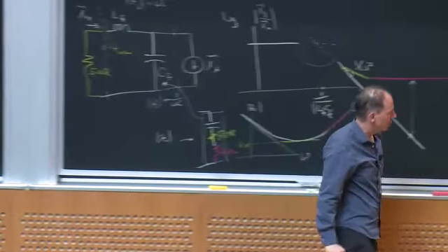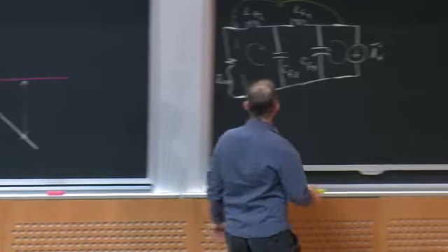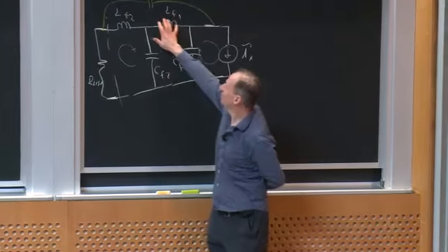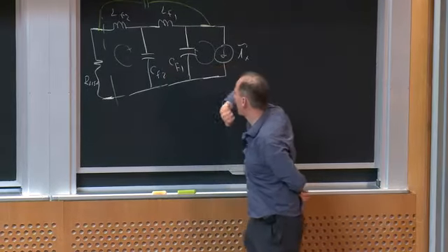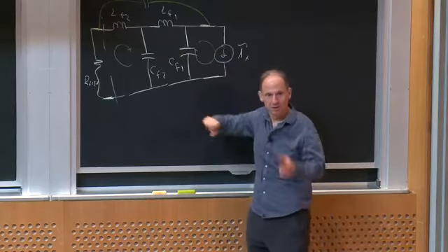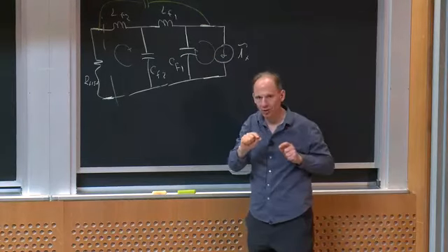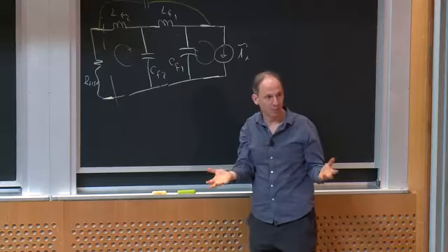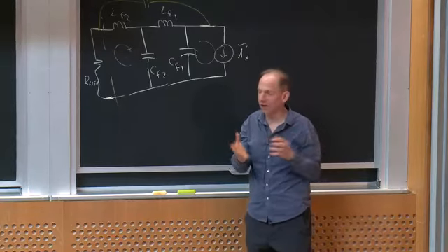But also, if you do a bad job, if you accidentally put a capacitance here, or because you don't place this capacitor very well, have extra lead length going to it, and you insert some inductance, you'll make everything worse. So you want to be really careful about your circuit layout.